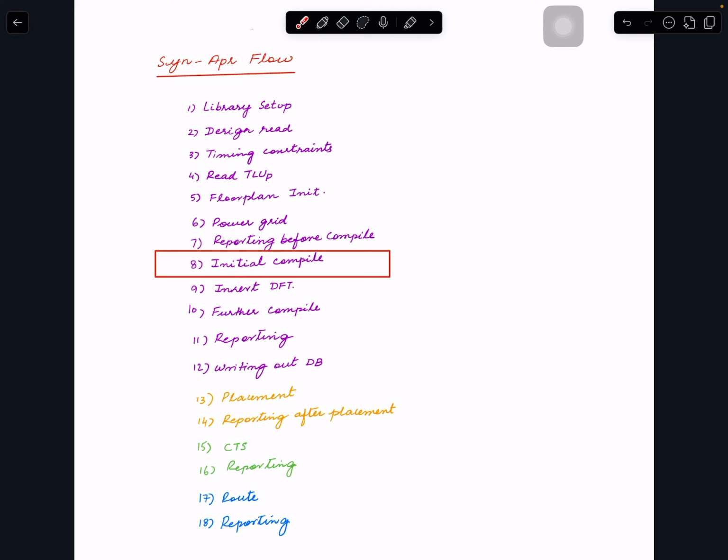But in order to see the effect of some of these constraints, the pin constraints and area constraints we give, for example, we can say give us a floor plan with 75% utilization, 70% utilization, or maybe you already have coordinates, you know the width and height.